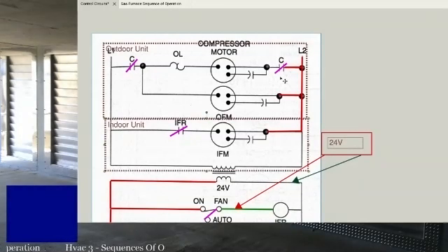Especially on a compressor, always get to the compressor and check the actual compressor terminals and make sure you've got good connections there, because a lot of guys will condemn units because they don't come on and it's actually just the wire at the compressor is bad. That could indicate other problems with the compressor itself, or it could just be a crappy connection.